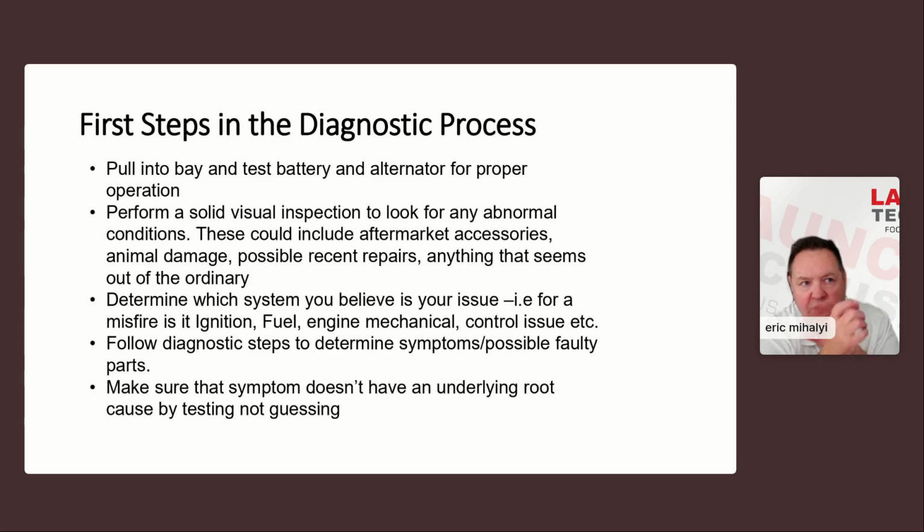But if you have a diode, right? An alternator produces an AC signal, and those diodes are a one-way check valve. They convert it to DC, so that it comes out of the alternator into the vehicle's electrical system as direct current, which is what we need. If one of those diodes goes bad, we can bleed some AC signal out into the car.